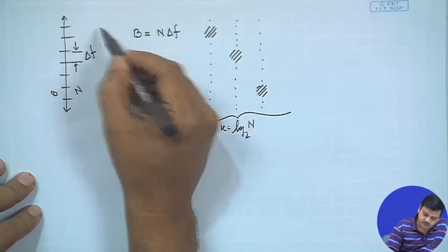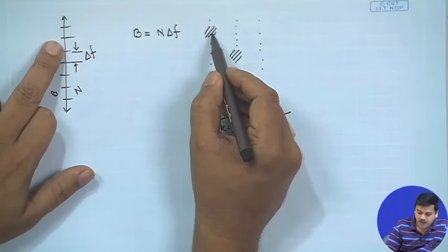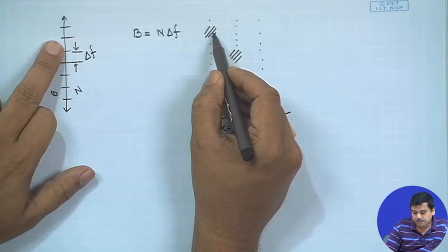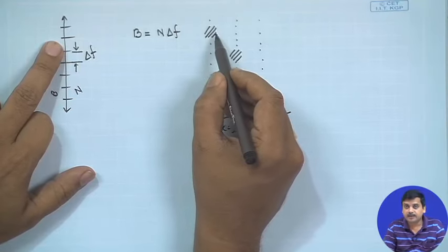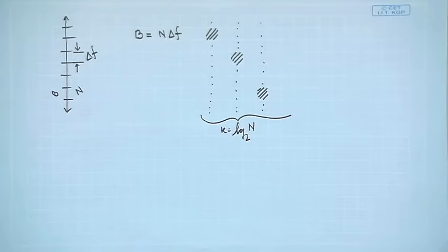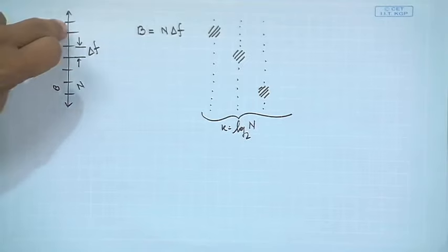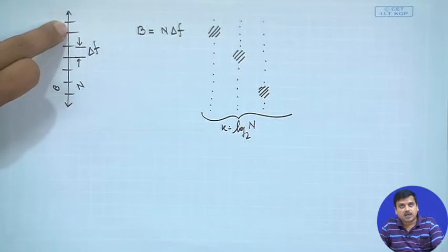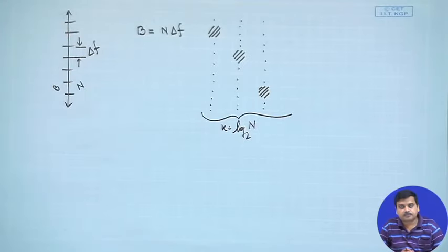Another more efficient way of doing this could be, if we get back to our picture here, why not choose one of these frequencies and send a PAM signal on top of it. That means not a binary PAM, but an M-ary PAM. So, I not only have n different options over here, but each one of them has another m different options.